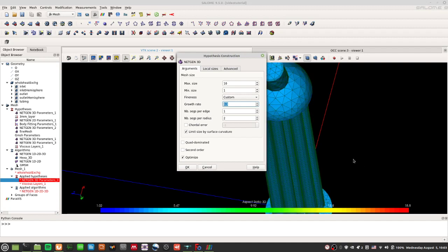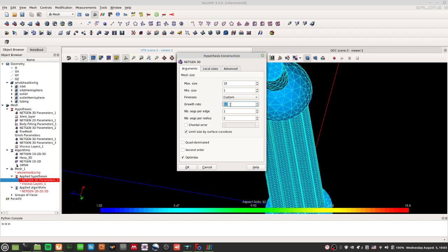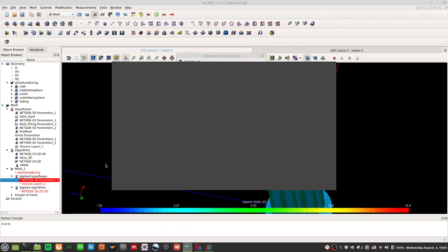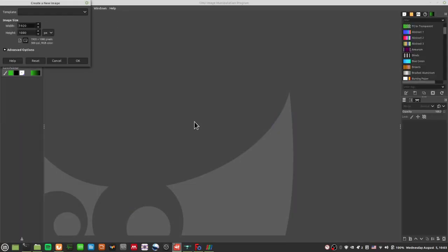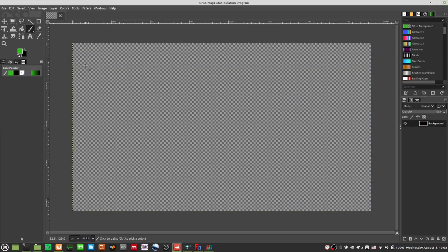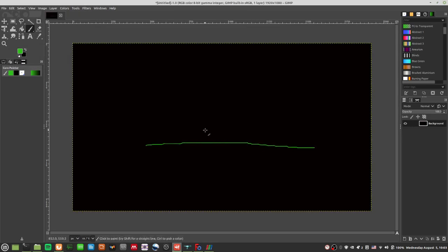So you can imagine in the center of your pipe, you'll have very coarse meshes, and towards the surfaces, you have a smaller mesh, which is what you should expect. If you have an average size of the mesh just adjacent to the wall, maybe this is 1 mm in diameter.